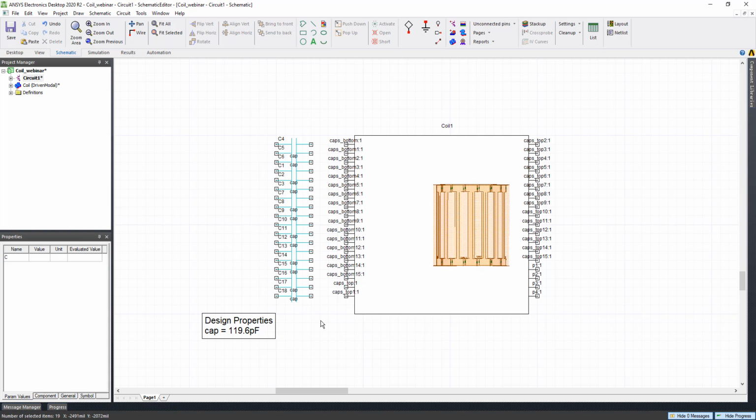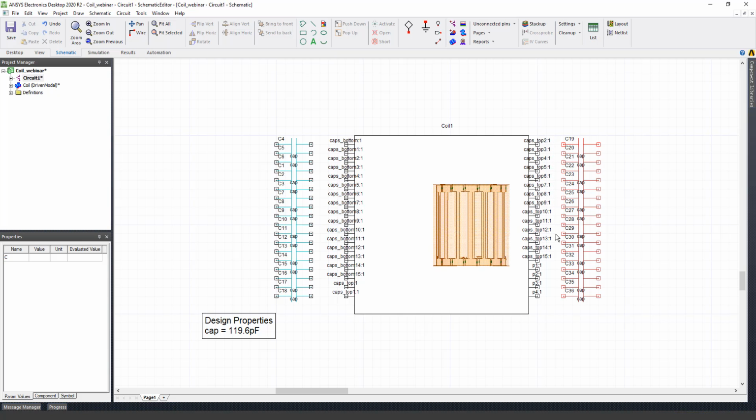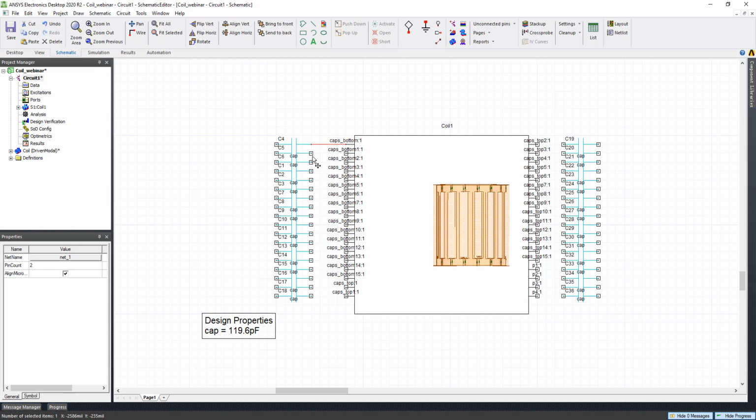All right, so copy the other one too. The good thing about setting up this variable is if you have the design parameters here, then you are able to run the parametric analysis. So you can actually tune your capacitor values up and down to see how it changes, etc. So I should also copy the wire. But yeah, this can be simple.